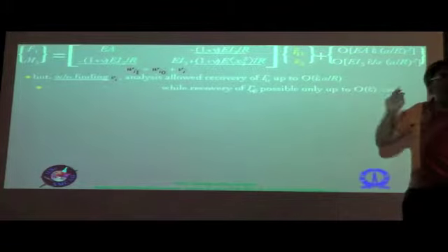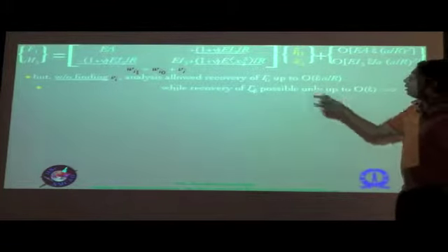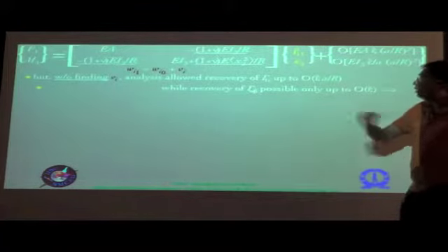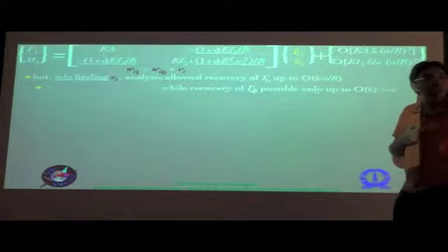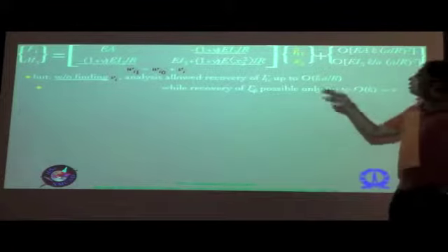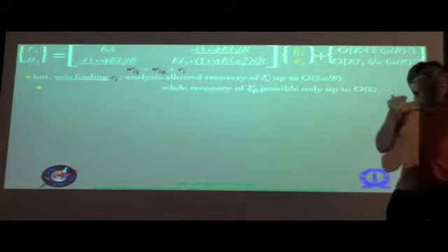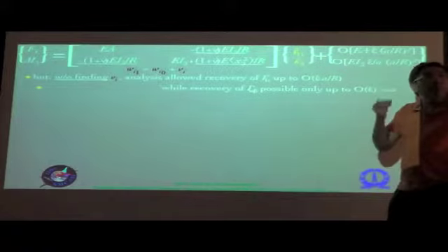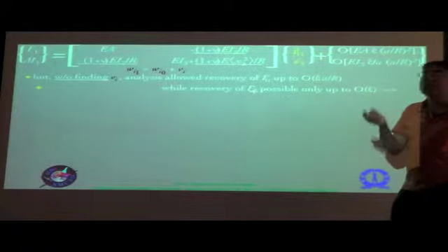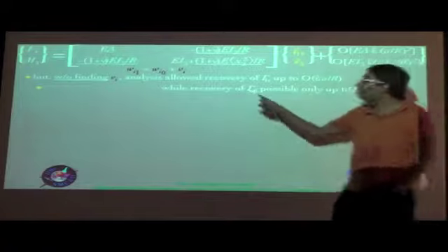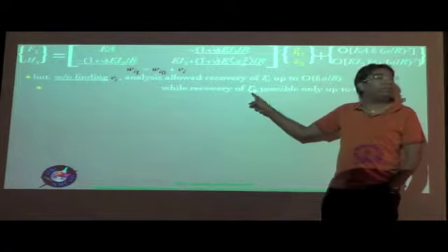because if you recollect, the gamma 1i, that is the strains associated with the one direction, the axial strain and the two transverse strains, those strains did not contain derivatives of the warping with respect to the cross-sectional coordinates. So it was only in the gamma alpha beta, that is in 2 2, 3 3 and 2 3.